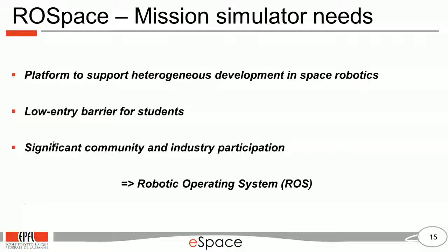These nodes listen to messages, do the processing, and publish their own messages on specific topics. ROS allows you to do that very easily by defining arbitrary messages and writing an easy wrapper around existing hardware that you design yourself.